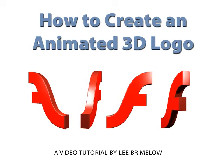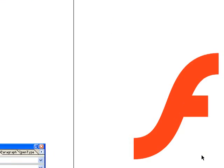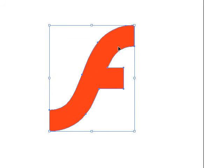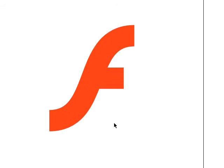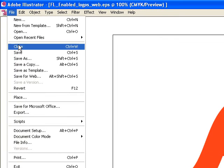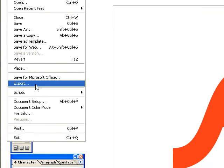Okay, in this tutorial I'm going to show you how to create an animated 3D logo for use in Flash. So here we are in Illustrator, and I've just created a simple shape with the pen tool, and this is just traced over the Flash logo here, and it doesn't have a stroke. And we're going to want to export this for use in Swift 3D, where we're actually going to create our 3D animation. So I'm going to go to the File menu, and I'm going to choose Export.